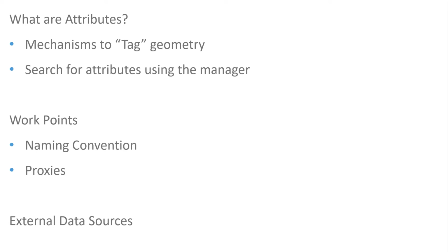So I can use the attribute manager within my code in order to interrogate a model to find edges and vertices and faces and things like that that have a tag on them, so that way I can place dimensions or even balloons. So it's a means for us to identify where that geometry is ahead of time in a predictable manner, as opposed to manually identifying where those are and then selecting them using the manual tools for generating a drawing. Okay, so what does that look like?